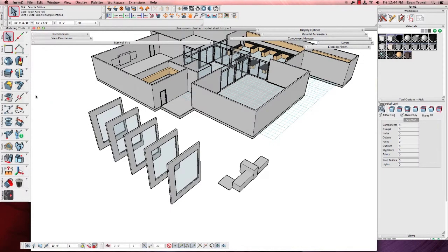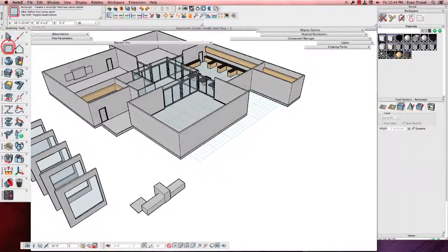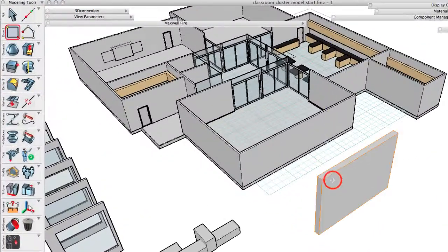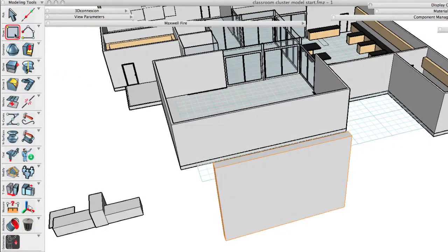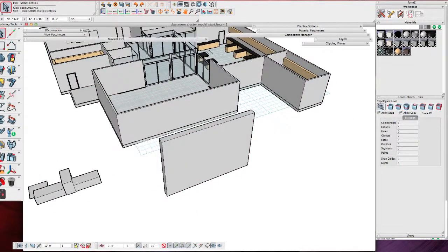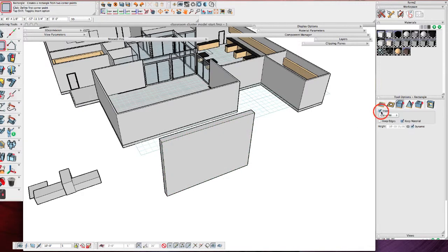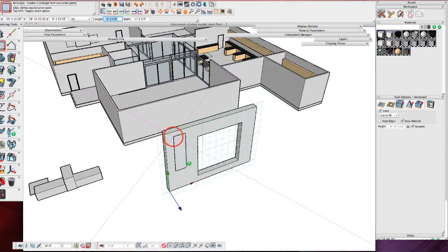All right. The next one, since the walls are Boolean, do you have different materials on them? Okay, so this is kind of something I think that's coming from the past inside of FormZ. One of the cool things about this now is that Booleans can be real time. So for instance, if I go here and I say insert, cut or fill, and I draw on this surface, I can just cut right through it right away. So that's one of the cool new things about FormZ 7, is that Booleans happen right away.